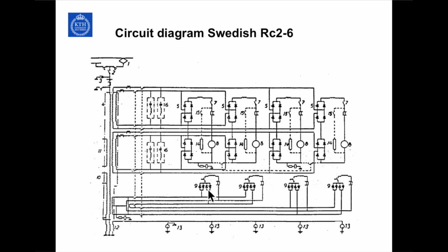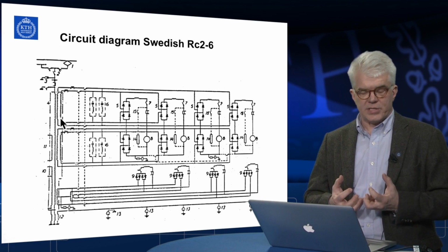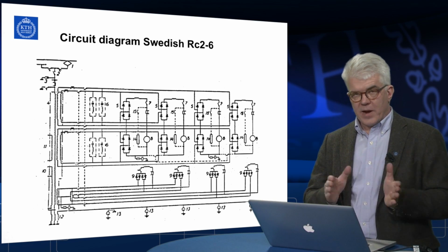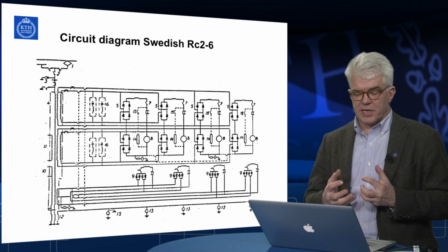This is a control of the field winding. Then you have the 2 thyristor bridges, series connected, and to the left you have the transformer, and this transformer has a low leakage inductance in comparison to the one we have at AC traction drives, where you have a high leakage inductance.